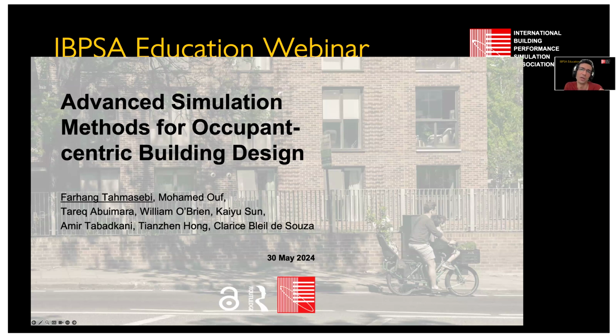That indoor temperature should, on that time step, go to your occupant behavior model. Your occupant behavior model interprets that and decides if, for example, an adaptive action happens or not. And if you open the window, then that already in the next time step should change the situation. So you need to have this runtime data exchange. That's a key here. For example, EnergyPlus in its runtime language allows that internally, but also allows coupling with external tools. So that was maybe one of the reasons that we used that. But I imagine that other tools could also do more or less the same.